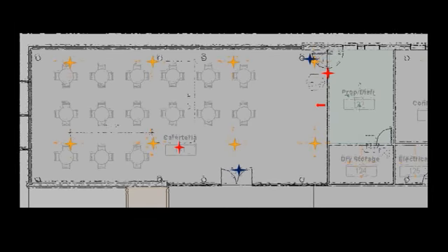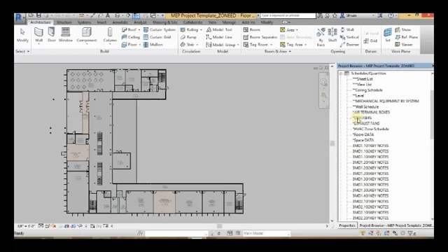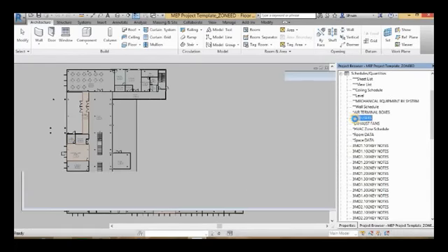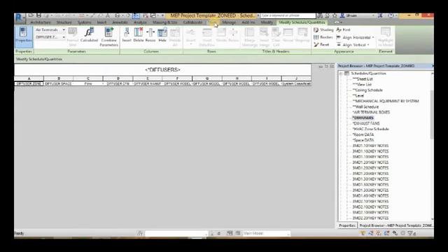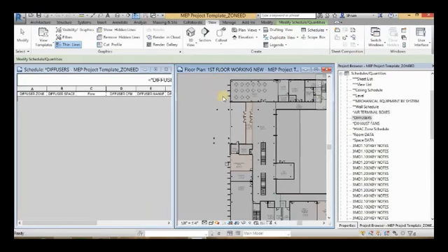So I hope this helps explain. I know we'll get into the script in a little bit, but this is what the end product will look like, and those are the rules on how we got there. Also, just like we found these door points, those could be windows to help us find something. That could be toilets in a room to put the diffuser right over that. Maybe equipment, whatever. So let's hop into this Revit model.